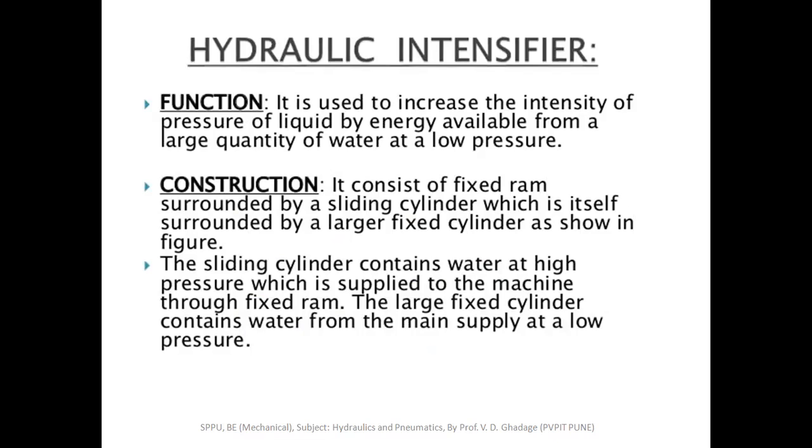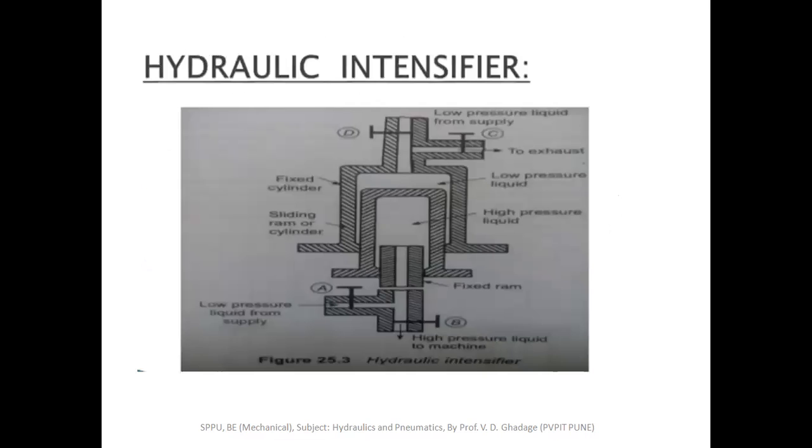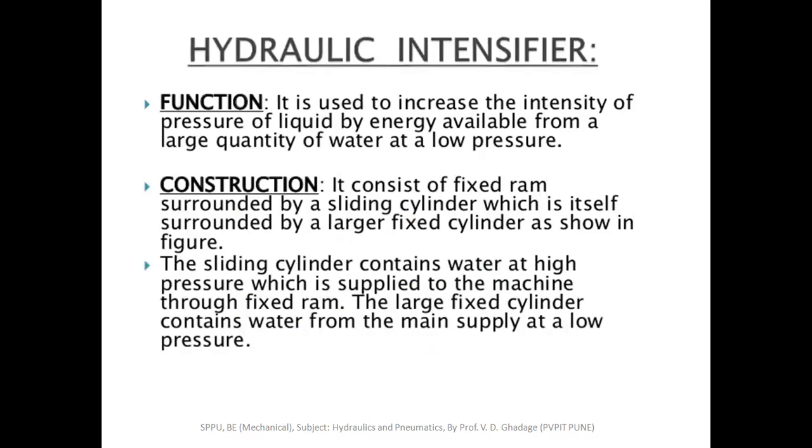Construction: it consists of a fixed ram surrounded by a sliding cylinder, which is itself surrounded by a large fixed cylinder, as shown in the figure. The sliding cylinder contains water at high pressure, which is supplied to the machine through the fixed ram.